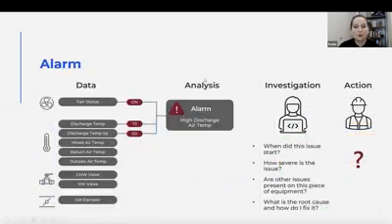All right, so we're going to do a little bit of a deeper dive of the difference between an alarm and a fault. Because I get this question a lot. Iowa would talk about this frequently. And so an alarm, here's an example, right? So you have an air handler again, and your alarm, let's say, is looking for a discharge air temp that's high. So if you saw an alarm come in as a technician, it just says high discharge air temp.